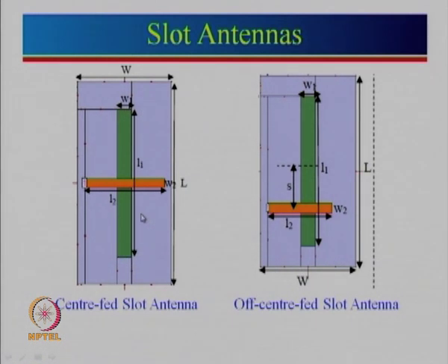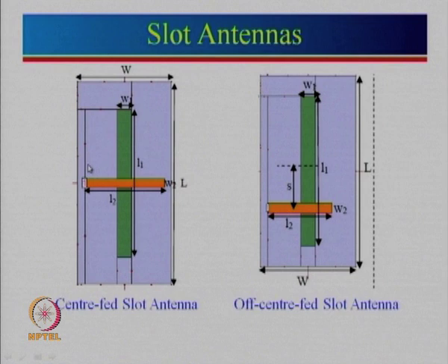Here I have shown a flat version. A dipole, normally, we look at as a circular rod or a circular wire. However, in a printed dipole antenna, we just take a printed configuration. So, a slot antenna is nothing but a complement of a dipole antenna. In principle, what we actually do is cut a slot in an infinite ground plane.